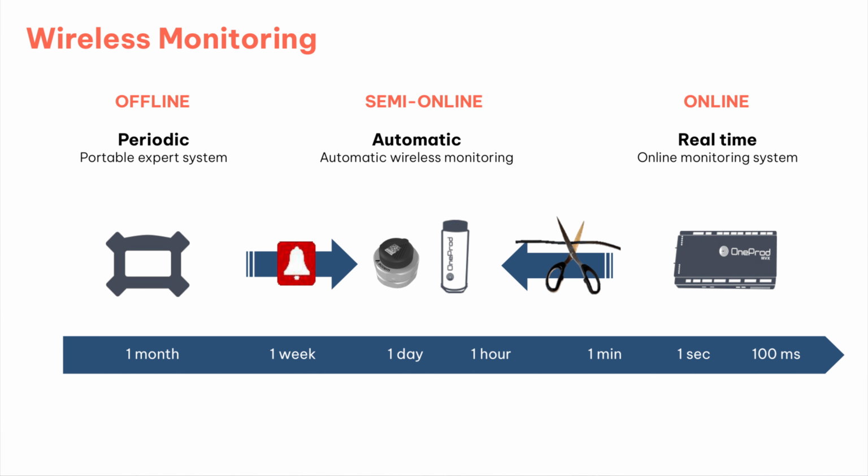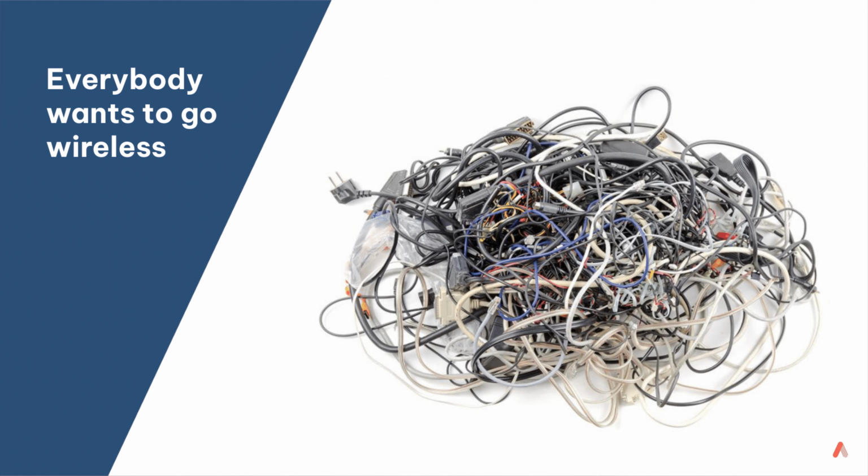The real benefit is cutting those wires and not having all that extra installation cost, but it should not be used to replace an online system, as it's really designed to take data a few times a day and not all the time, every couple of minutes. So everyone wants to go wireless. There's a cost involved with installing a wired system.